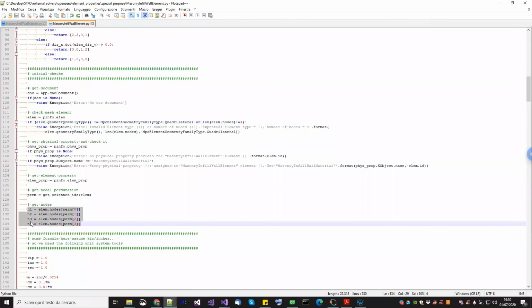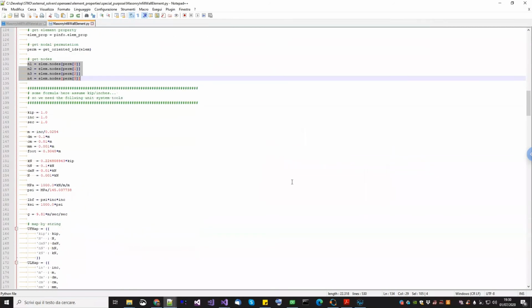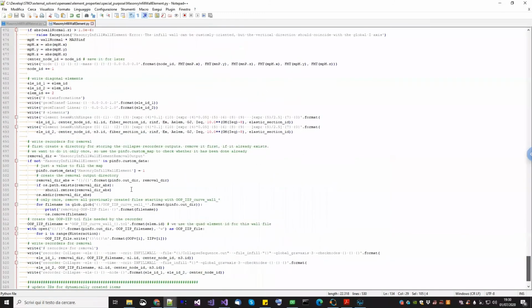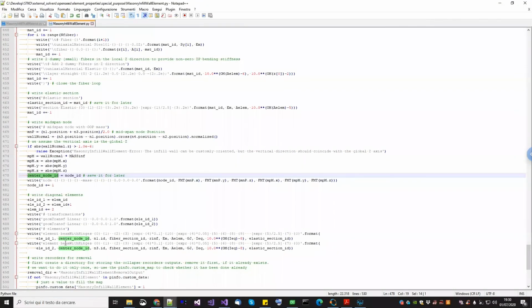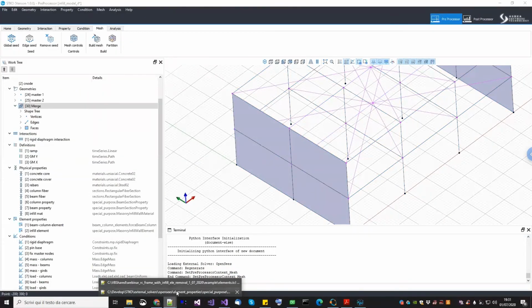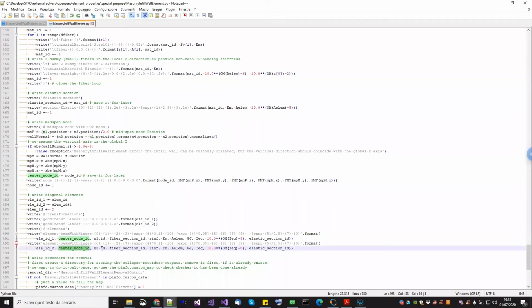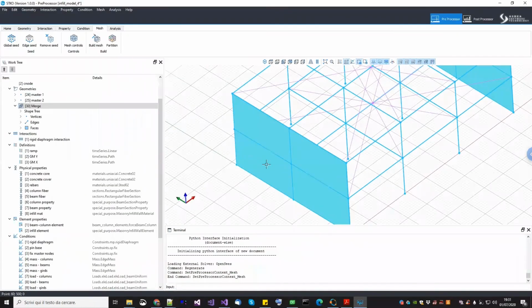Now the 4 nodes of this one are the same nodes used by the surrounding frames. So then, after doing all the calculation, at the end, when I create the extra node, let me go here. Okay, right, extra node. The extra node is not in STKO, but I create it directly in the TCL file, which is here, and I give it a tag called center node tag. Then when I create the two beams with hinges, I create these beams from the center node tag, which has been created automatically by STKO, to the node number 1, which is present in STKO, which could be, for example, this one. And then I do the same with the other, and it is connected from center node to node number 3, which would be here. And that's why they are all attached, okay? Because the initial quadrilateral element has been attached with the surrounding frame through the Boolean operation, okay?